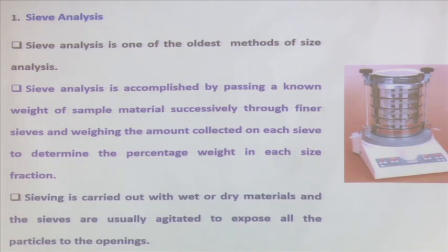So, that is the initial size distribution, the pie chart I have shown. That data you can generate out of this test. Suppose I have started with 1 kilogram of material, after 10 minutes when I have stopped the machine, I will take it out and then for each sieve there is a range, because I say that this much of particle has passed through the aperture of this screen, but was retained on this. It is like what I discussed yesterday about the sink float, the same thing: it is finer than this sieve, but coarser than this sieve. Okay.